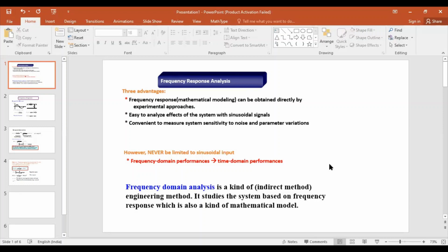So what is time domain analysis? We can easily define it as an approach to find the time domain behavior of a system using some mathematical model, which is nothing but the second order transfer function we had, and then we wrote the expression for C of t for different zeta. Then we wrote the time domain specifications. So all those things we did using some mathematics. This is also a similar approach, but now with respect to cos and sine or sinusoidal things.